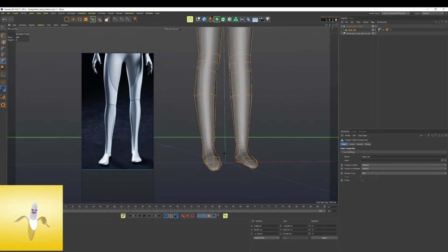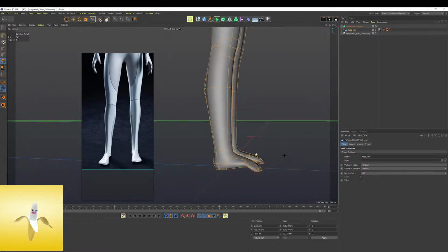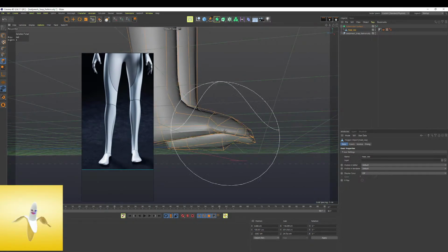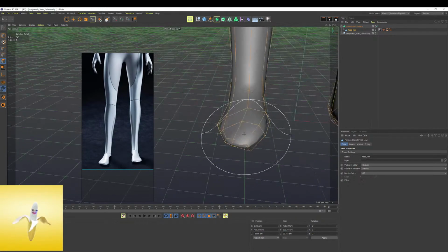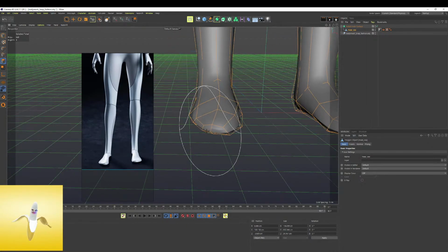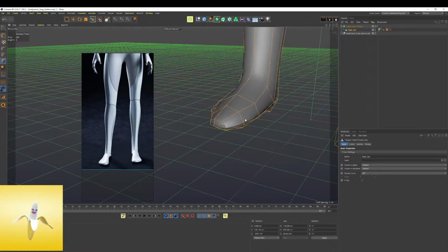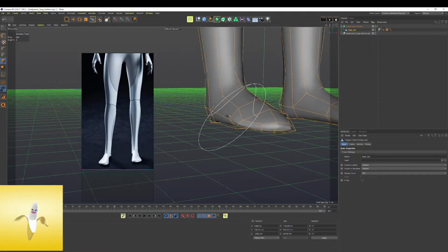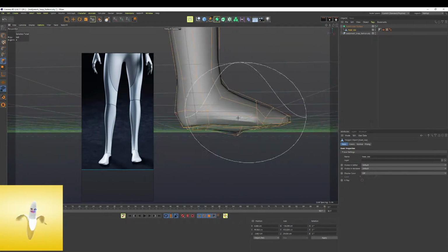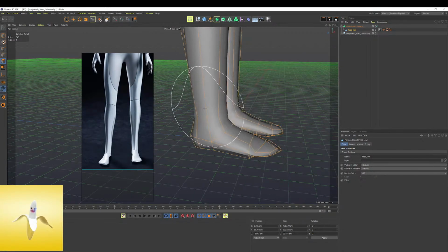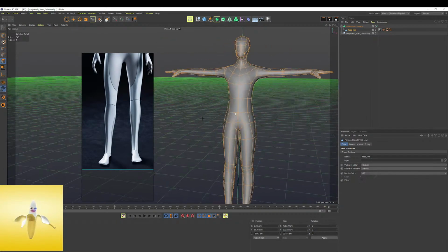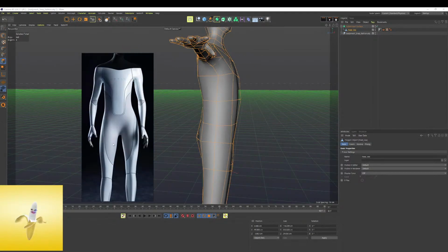Oh, let's look at the feet. I should probably get these feet to look a little bit more pointed forward, because when I rig this up, it will confuse it if the feet are at an angle like that. So I'm just going to bring those feet down to a resting position and swivel the nose of the foot forward a bit, and then bring up the side, and try to get this as flush with the floor as we can, just so that rigging is not going to be a problem. I'll probably use auto rigging for this. I'm not feeling like doing complete custom rigging tonight either, but auto rigging, yes.